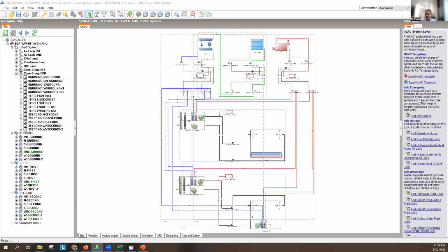And in Australia, you can't put that inside an occupied space. Okay. So they are coming up with things called hybrid systems. You may want to look at some of that as well. Okay. You can model them in DesignBuilder. The water-cooled VRF systems is what we call them. So in that case, the refrigerant is not spread that widely, but it is still something to be aware of. Okay.